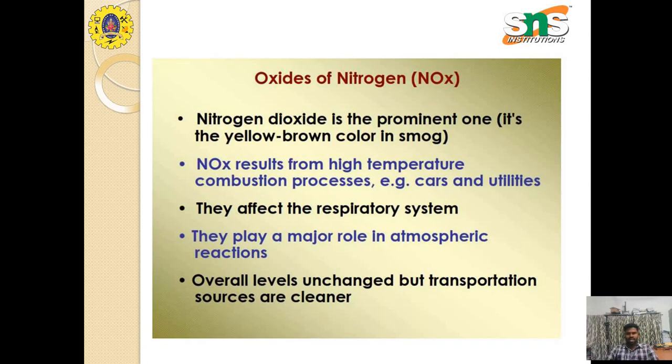And then oxides of nitrogen. These are produced during combustion because of the excessive amount of heat generated, so we have coolant circulation among the engine components to control the excessive heat generation during the combustion process. Excessive heat generation is the cause of the development of oxides of nitrogen, and proper heat circulation in the outside layer of the combustion chamber may lead to a reduction in the oxides of nitrogen.